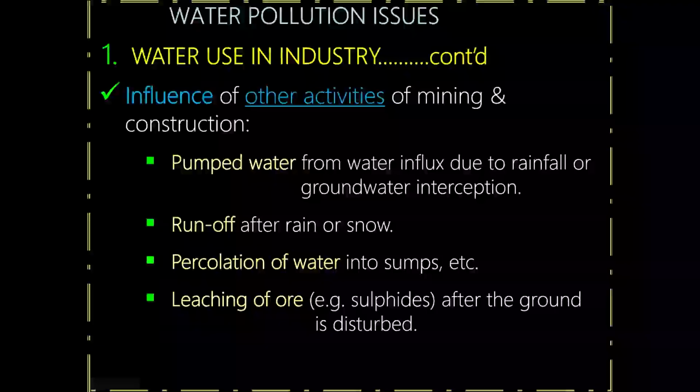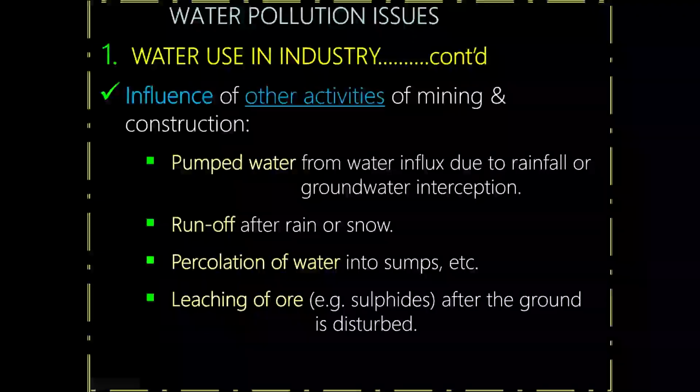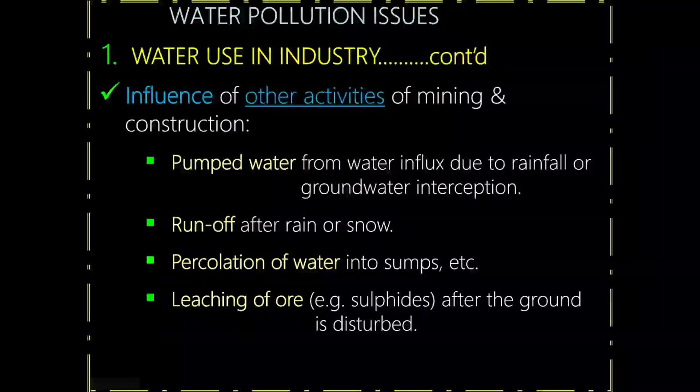There are certain rocks that have sulfides in them. They don't have any problem until there is presence of oxygen and water. Like we are saying, when you are drilling down, you meet water, and if this water comes into contact with rocks that have sulfides and there is presence of oxygen, then they would leach or turn into acid mine drainage.